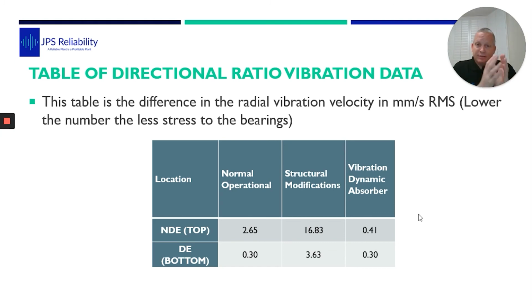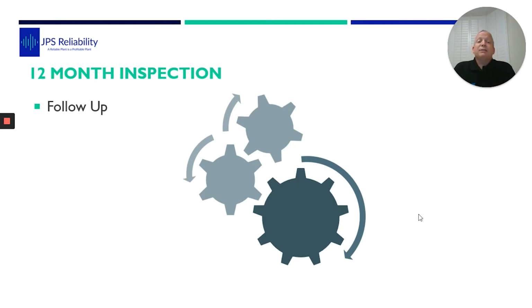But that was our theory, is that what we're aiming to do is absorb the energy. So we went back after 12 months, and they said to us, one of them's not working. So it's been going for 12 months, hasn't failed yet. So touch wood, we're looking like we are actually doing it. We're absorbing energy, and the problem was the whipping in the motor was stressing out the bearing, putting too much dynamic load to the bottom bearing.